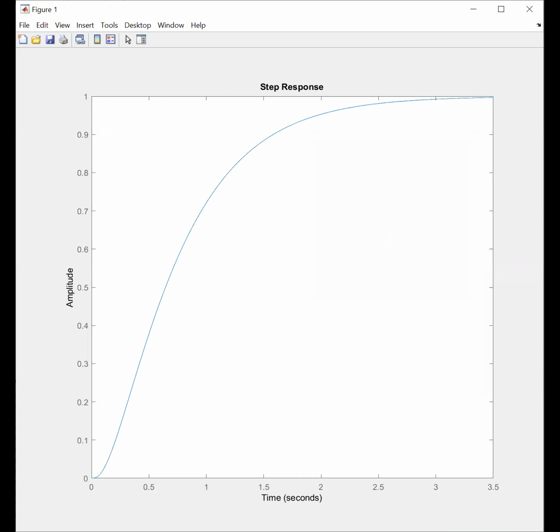So now, if you noticed, earlier step response was a straight line. It went from here all the way to 25. It didn't converge. It didn't have a steady state value. But as soon as I converted an open loop system into a closed loop system by adding a unity feedback and a gain, now my system response has kind of got bounded. I can right click and then I can add the characteristics.